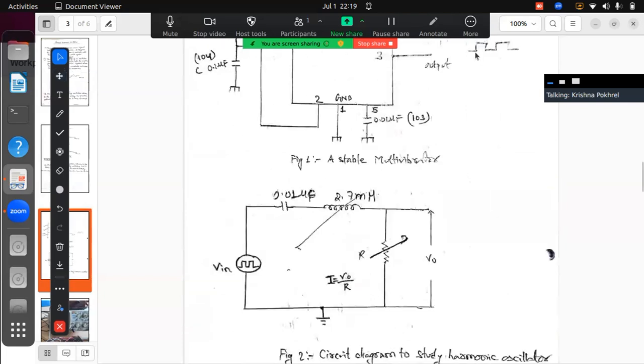Now for this wave will be supplied here. Okay, this one wire we will connect to a 0.01 microfarad capacitor. The 0.01 microfarad capacitor is marked 103, or you will be given a capacitor of the same size in your lab. Make sure that one wire of this will be connected to the capacitor and the other wire of the capacitor will be connected to the inductor.